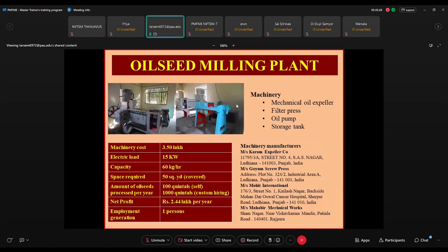What types of impurities can be soluble in the oil? Like color or color pigments. Color is a soluble impurity in the oil, and we have to remove that. So in the refining process, we have bleaching action or decolorization. This is one unit operation.